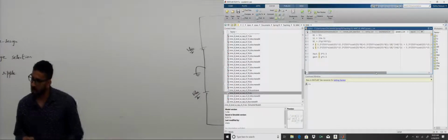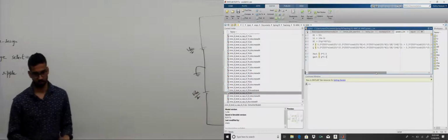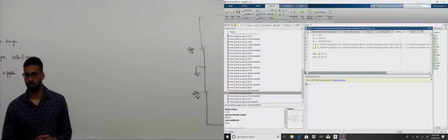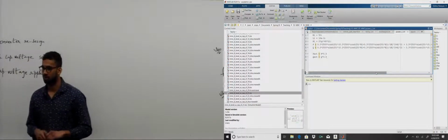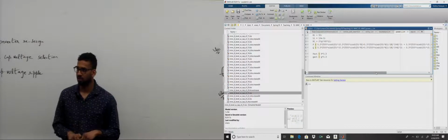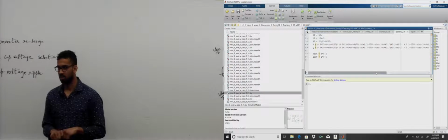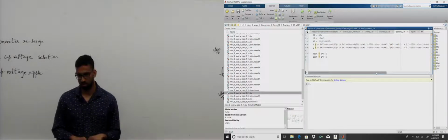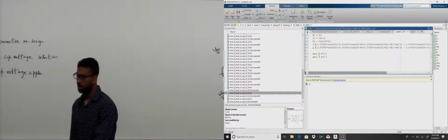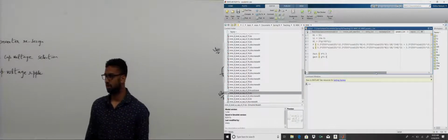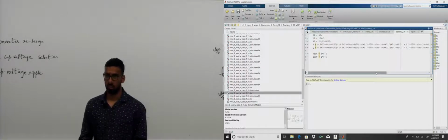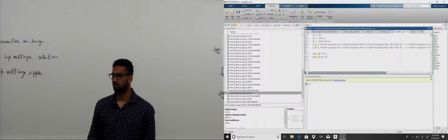So you showed those 2 equations. And clearly you have 2 equations. So what Abhijit said, you think about what he said. Yes, Q cannot be 0. That's right. It cannot be any arbitrary P and Q. But given P and Q, you can find amplitude and angle. Right? So we can find MA and alpha, but maybe it will be out of range. See, MA may be greater than 1, which is not really feasible. So for feasible solutions, P and Q should be okay.